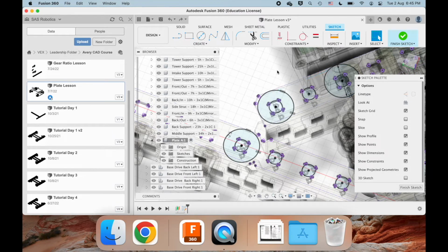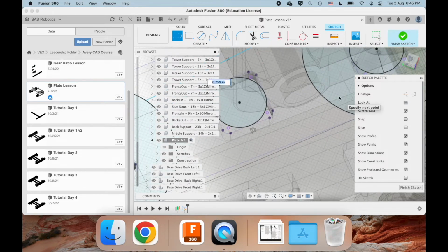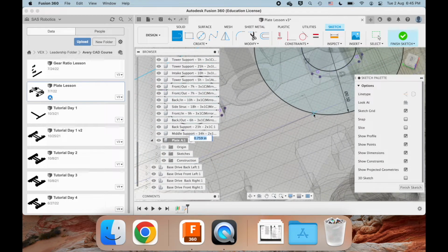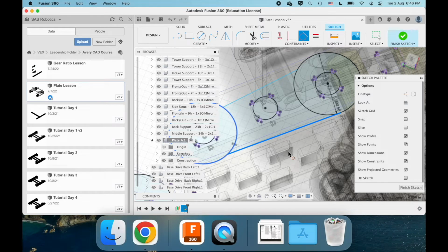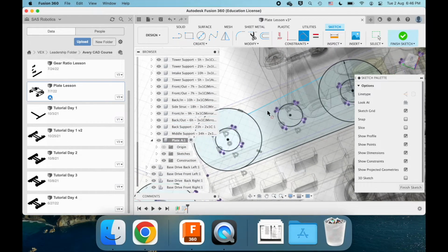Didn't want that. Here, here, here, here. You want to be careful where you click down. If I click down here, that's going to actually create a coincident constraint, meaning that this line's now bound to this sketch line here in the circle, and that means I won't be able to move it later with a tangent constraint to properly align it like this, as I'm showing you, right? Tangenting this together. That's what I really am going for here.